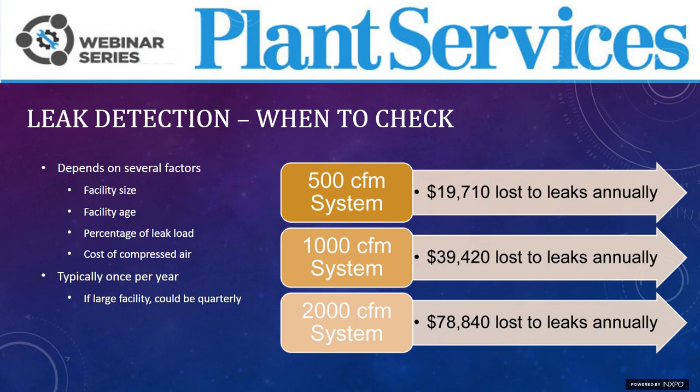You know, leaks are going to occur over time. The type of piping material, the age of your facility, the size of the facility, all of these things are going to influence the number of leaks you're going to see. Facilities that have only one compressor may only need to check for leaks every year, but it really depends on the size of that compressor as well.